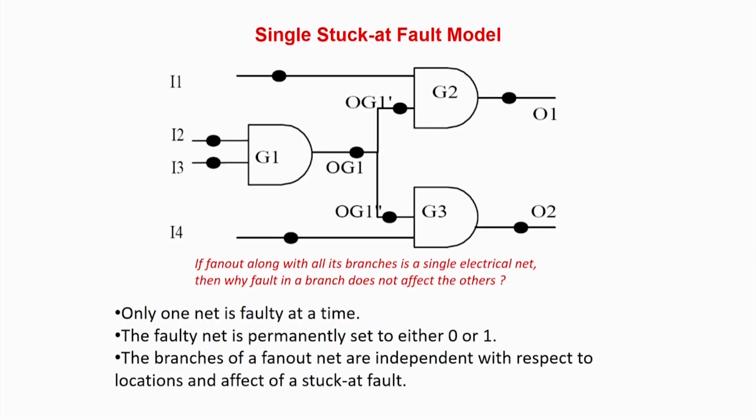Again, we discussed that the single stuck-at fault model is one of the most widely accepted fault models, because until the last 10 years, if you could verify that there is no single stuck-at fault, the circuit could be considered to have no faults, and the correlation was also very high. So what was a stuck-at fault model? You assume that each of the lines of a circuit can be either stuck-at 0 or stuck-at 1, and you have to verify by test pattern application that none of them occurs. Generally you call it the single stuck-at fault model because you consider only one line at a time. This is the first fault model on which almost every circuit test was based.